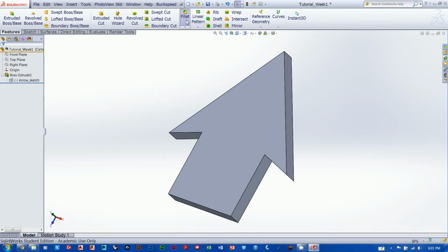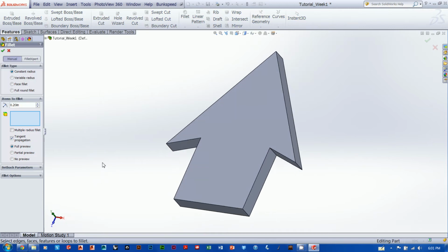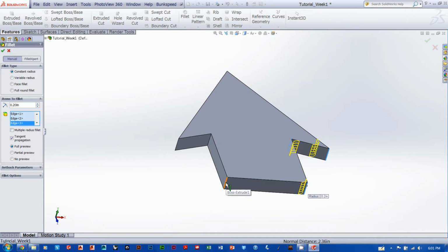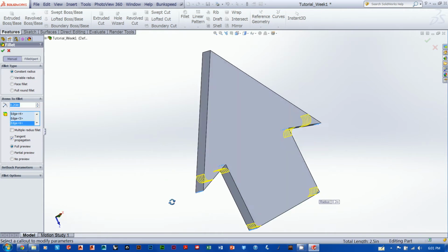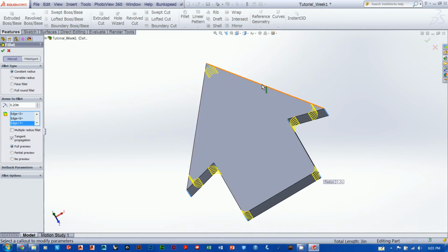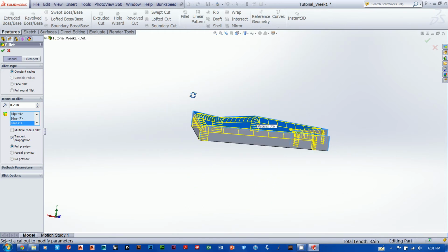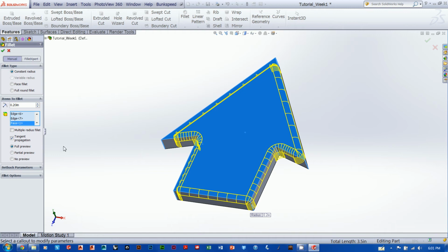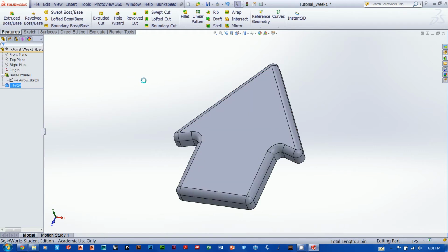We added some fillets in our last one, and I guess we can add some more fillets back because it's fun. It's easy to add fillets in SolidWorks. Just go right along here. Throw in some fillets for no big reason at all. Why not? Just to show you guys again how simple it can be. You just click on an edge that you want to add a fillet to. If you want to add a fillet that goes around the entire perimeter of your shape, you just click the face that you want to throw a fillet around, and it'll add a fillet for you. Just hit the green checkbox to confirm that. We did a constant radius fillet there, which is where you add one single size fillet to all the things you click on. There's a couple other different kinds of fillets here that we could talk about later on too. Green checkbox just to confirm.